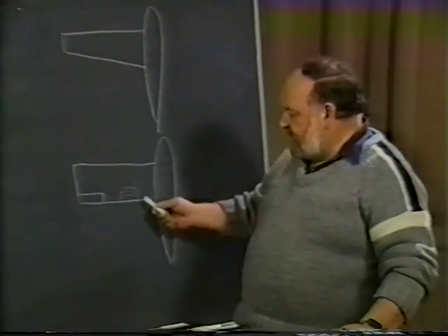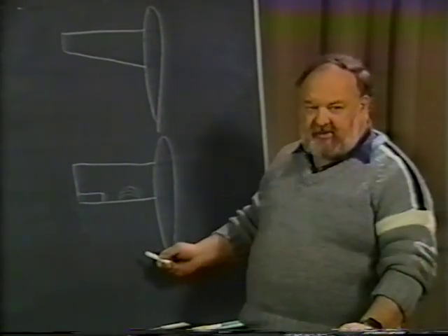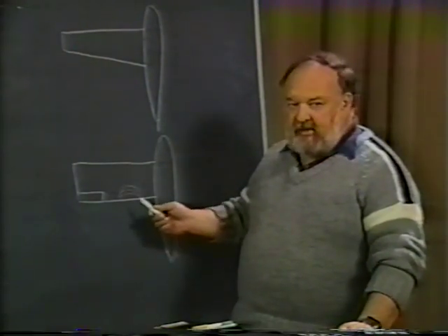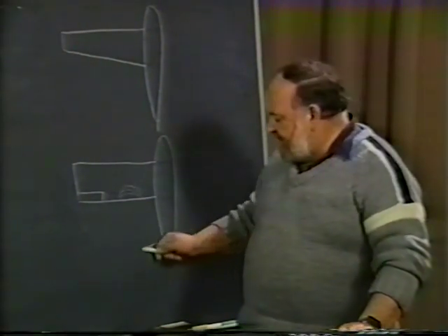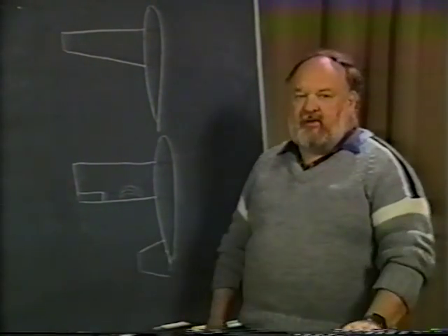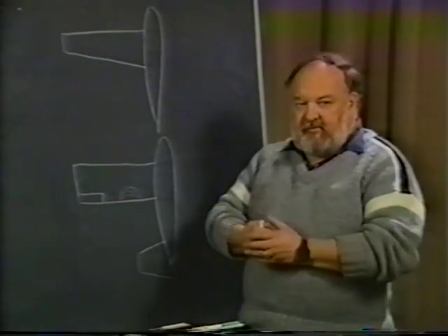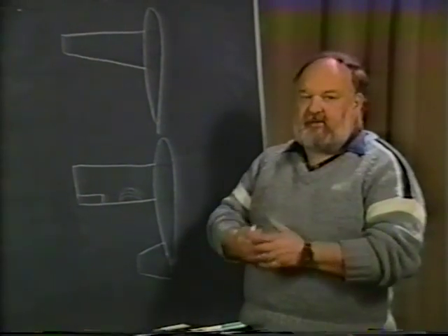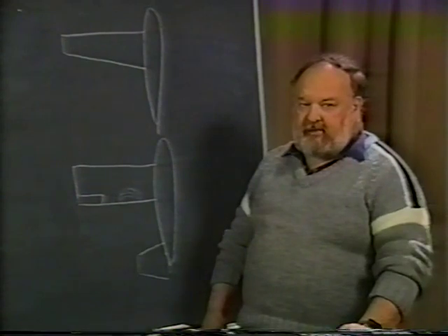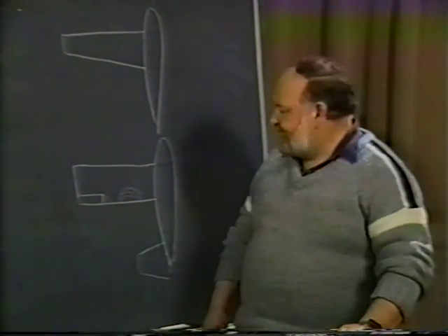A little side effect to it too, if you have a standard tail configuration in the back, by getting flow separation beginning inboard like that, this turbulent air will then start to impinge upon the horizontal tail, and the pilot himself will actually get more stall warning, because he'll feel it within the stick, because the horizontal tail will sit there and start vibrating and shaking a little. This is a real good stall warning system. Without a question about it, that's a good way to do it.